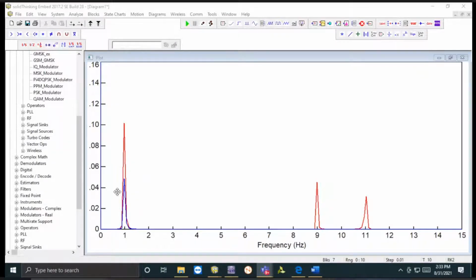So this red one and blue one are overlapping. You can see here, this is your sampled version of the signal and the message signal. They are overlapping and they have an exact match. There is a variation in the magnitude only, and this is because of the frequency of the delta function, the train of impulse, which is 10 hertz, right?